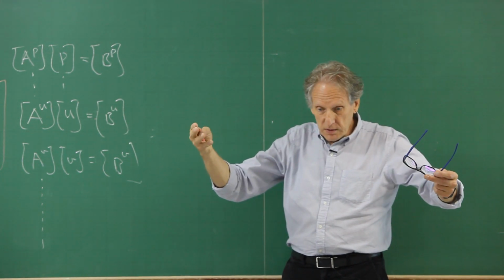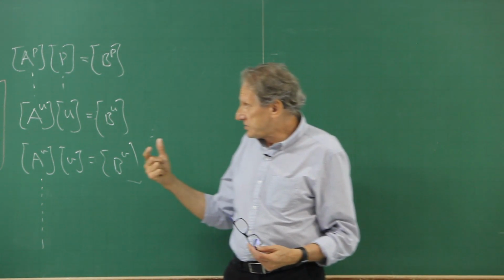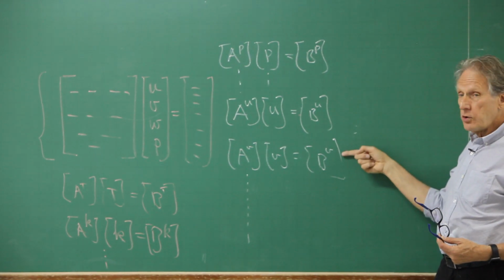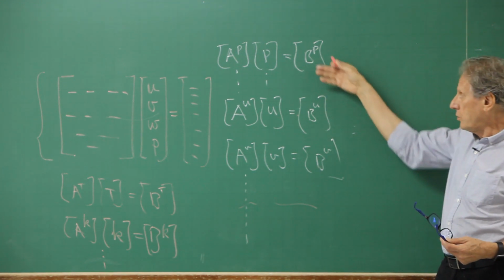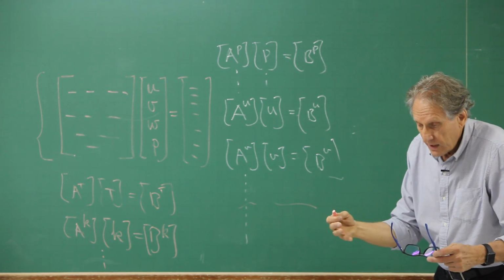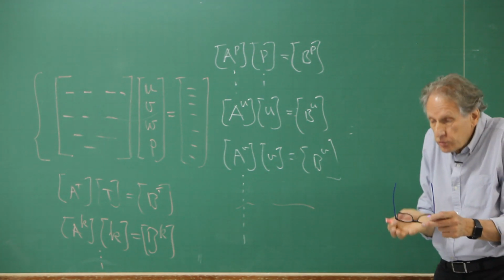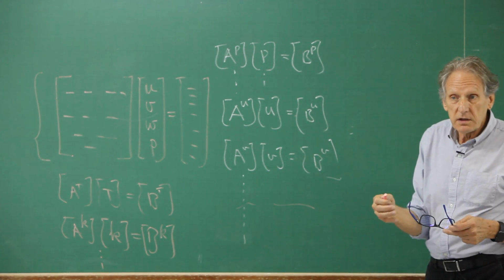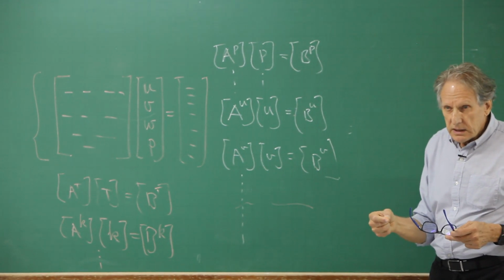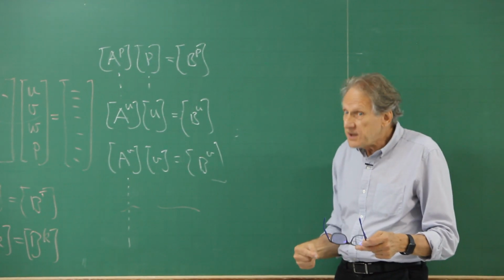So at the end of the problem, you solve the coupled problem. But then it's better to say simultaneously, because in the segregated case you are not solving U, V, W, and P all at the same time. The solution is one, then the other one, then the other, and then this is segregated. But when I put all together, it's simultaneous. Segregated is a synonym of, let's say, one after the other one, after the other one. So they are not at the same time.